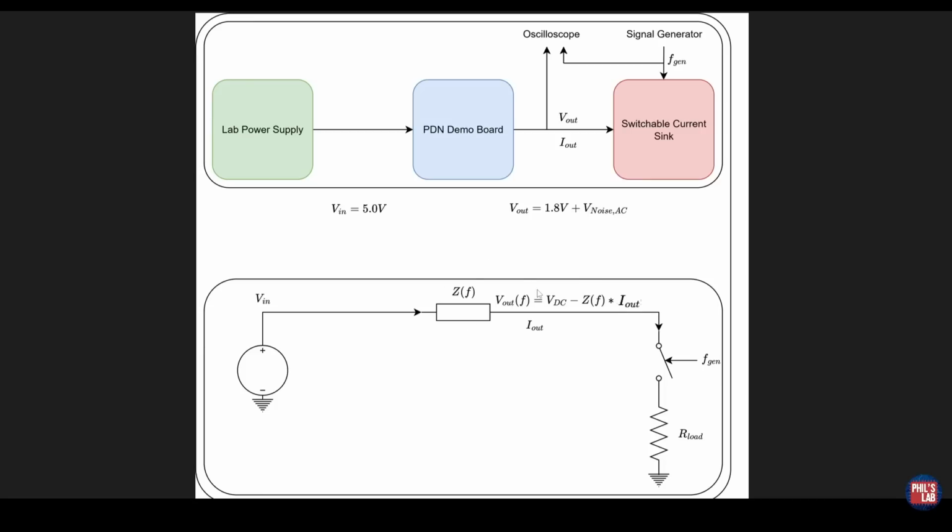Therefore, if we have larger impedances at certain frequencies, and for instance our MCU or FPGA is trying to draw a lot of current periodically or with transients, then of course that impedance will play a part. And if we get too large of a voltage drop, we might get brownouts, we might get EMI and signal integrity issues. So that's why this is so important. But now let's move over to the lab setup.